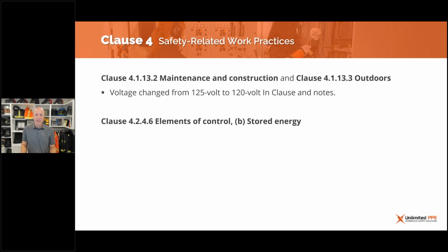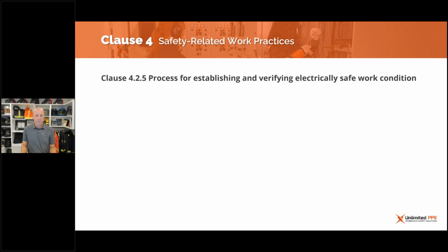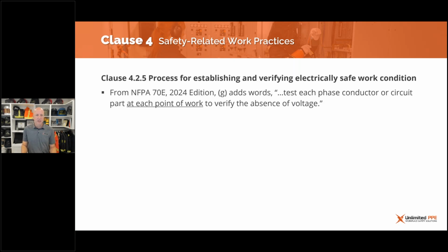Maintenance and construction, and the clause for outdoors. So we've just updated some of the terminology here. And we get back into the process for establishing and verifying the electrically safe work condition. There was an important change that was introduced. I mentioned previously how we have a lot of emphasis put on the necessity to achieve an electrically safe work condition, meaning that the equipment has been de-energized and verified as being safe.